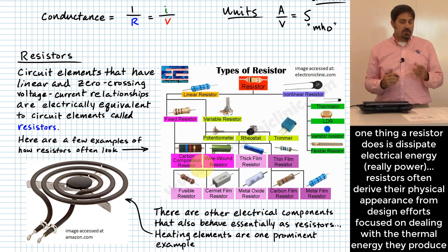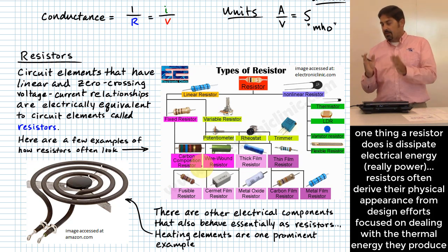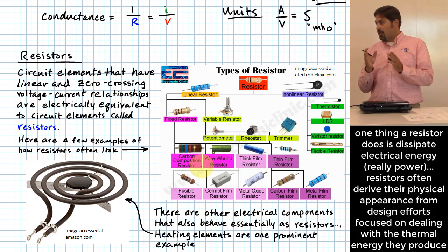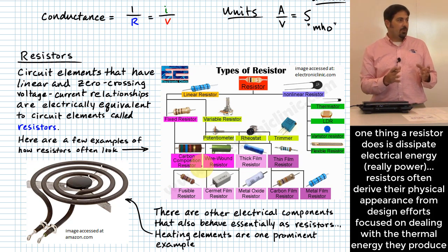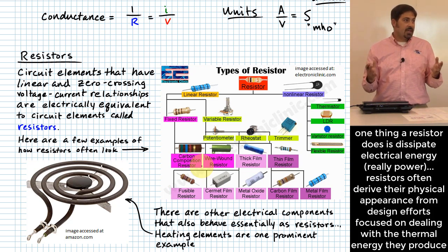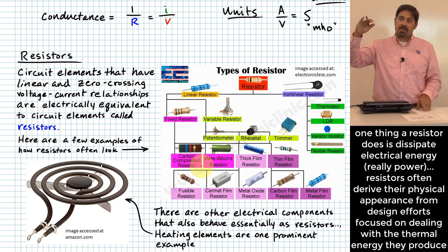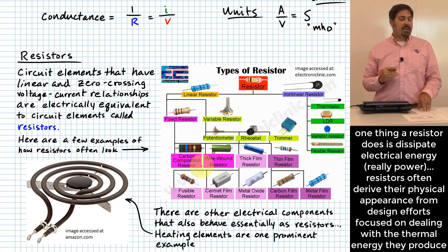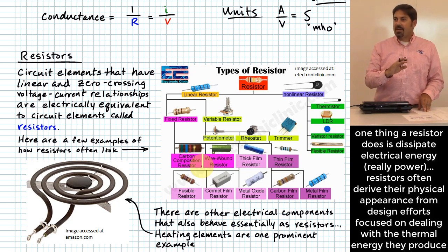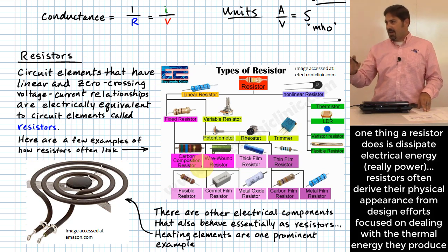And so with resistors, what they do is they take electrical energy and power and they convert that electrical energy and power to what? Heat. And if it's continuously producing heat, which is essentially thermal energy, what happens to temperature if you don't get that heat out of there somehow? That temperature will keep rising and rising, and eventually some of how you thought those materials might behave at one temperature, they might not behave that way anymore at a much higher temperature, right?